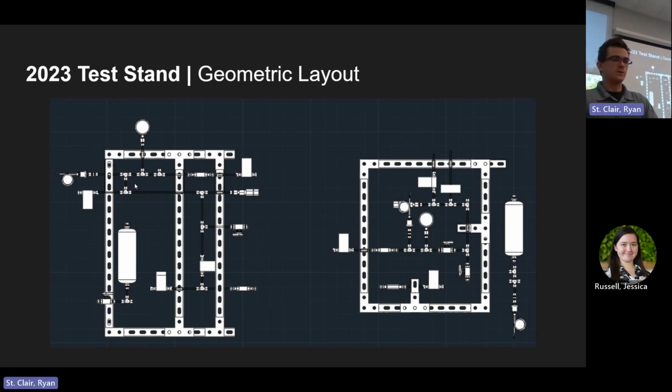One other thing that's more clear here, that wasn't very clear in the P&ID because I forgot to mention it, is that there's a path for nitrogen gas to go from here down through this T fitting, over through here, and actually bypass this ethanol. We do that because we want to be able to tell the system to flood the combustion chamber with nitrogen gas, basically making a very inert environment at the click of a button. So we can control this valve on or off, and it will sense this pressure and this pressure. Actually, this pressure will be higher than this. So you can turn this off, you can turn this on, and you'll have nitrogen gas flood the system.